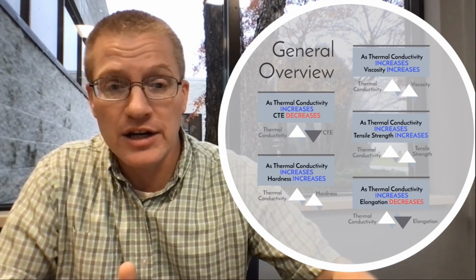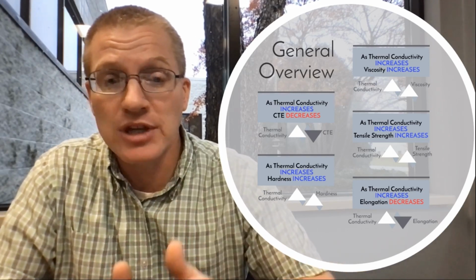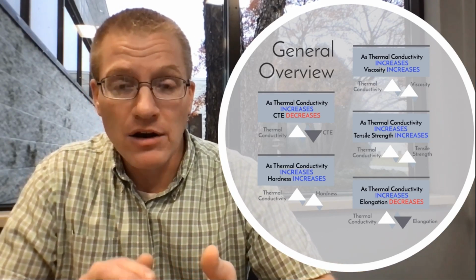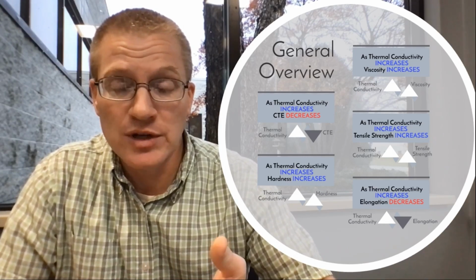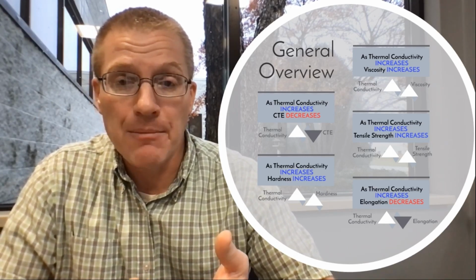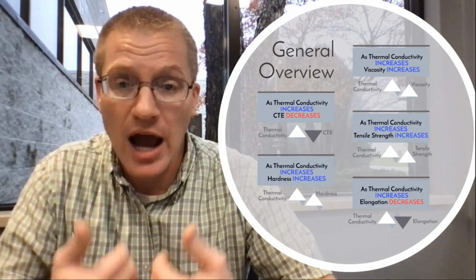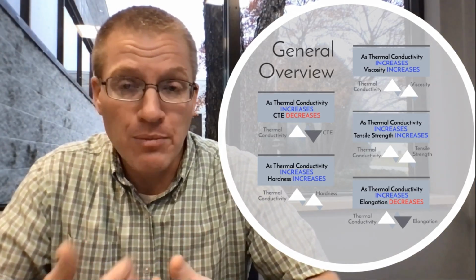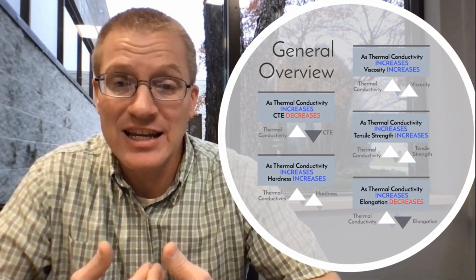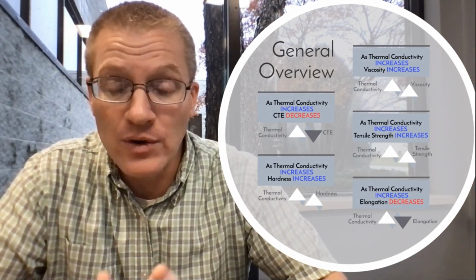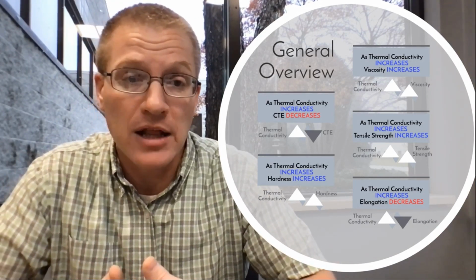Same thing on the hardness, right? When we're looking at hardness, same thing is going to happen. Hardness is going to increase as we increase thermal conductivity, mainly because we have to increase filler loading. Again, a lot of this comes down to how many filler particles we have in there, and how its hardness is influencing the hardness of the polymer.